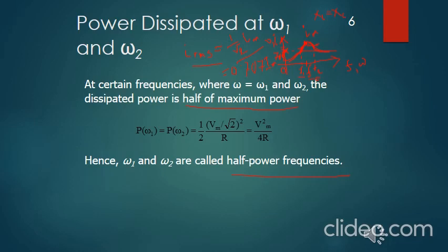And for this RMS current at that position, you know that the power will be half of V square divided by R, and this V is RMS. So just put the value of RMS, that means V is equal to Vm divided by root 2, as I have told you that I RMS is equal to 1 by root 2 Im.